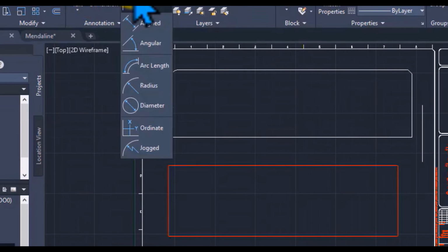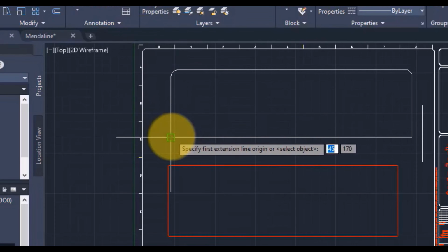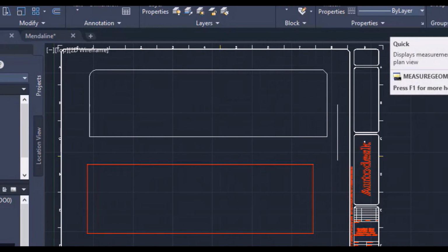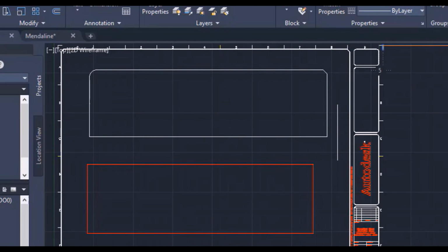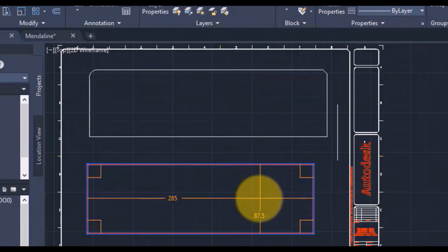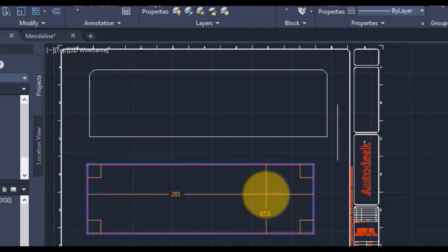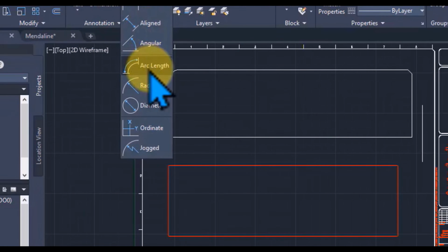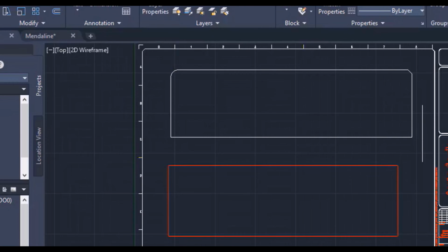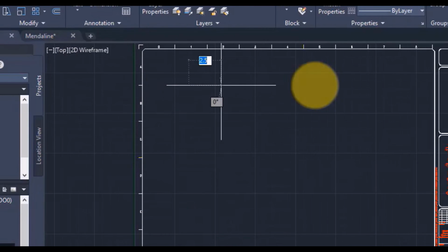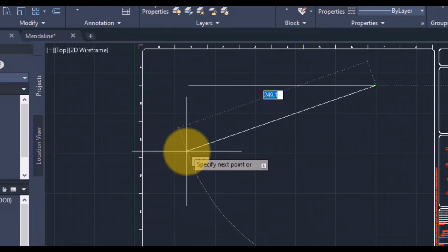Scoot is essential. If you use standard move on a component, the wires detach and they just stay behind. You've broken the circuit. But if you use scoot, it's like the wires are made of rubber bands. You move the component and all the connected wires stretch and move right along with it. The connection is never broken. It's stretching the logic along with the geometry. That seems like a mandatory workflow change. It is. If you aren't using scoot, you are literally redrawing half your work every time you make a small modification.